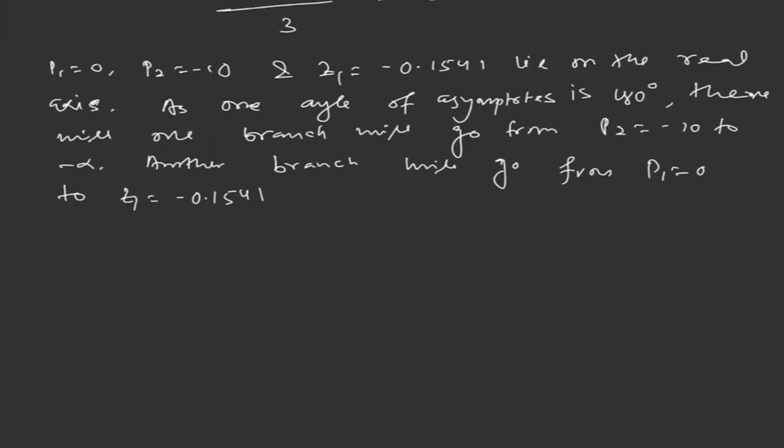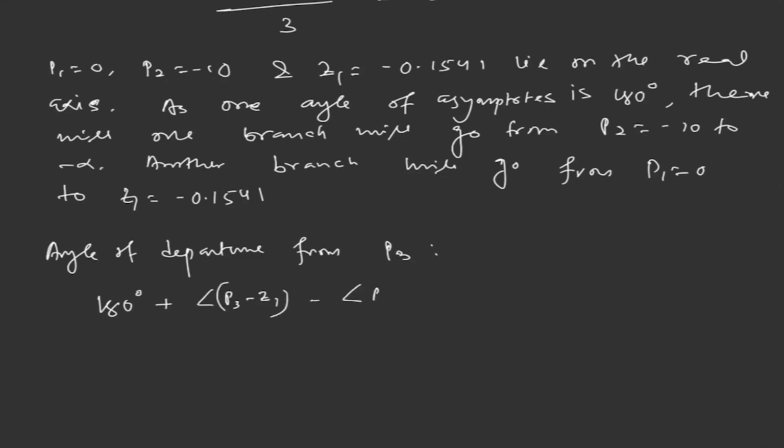First, let's find the angle of departure from P3. It is 180 degree plus angle of (P3 minus Z1) minus angle of (P3 minus P1) minus angle of (P3 minus P2) minus angle of (P3 minus P4).